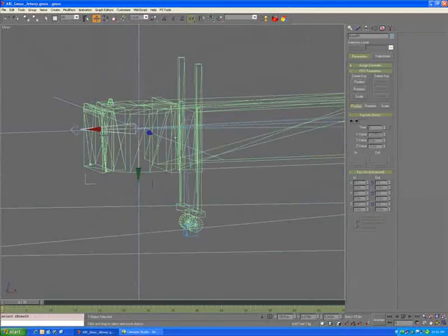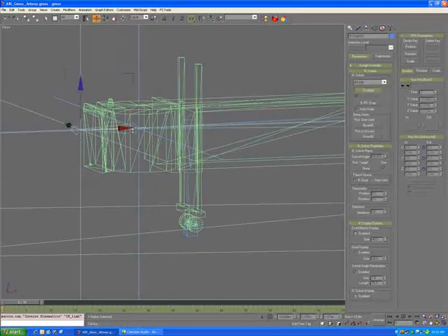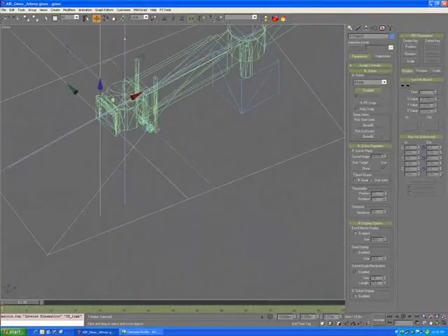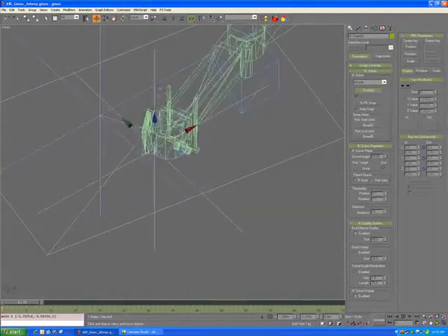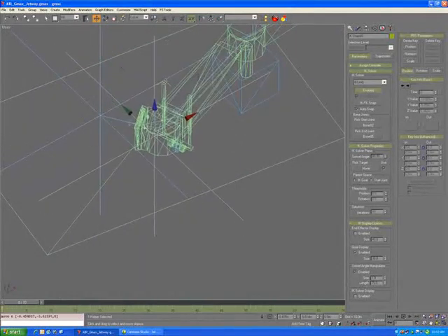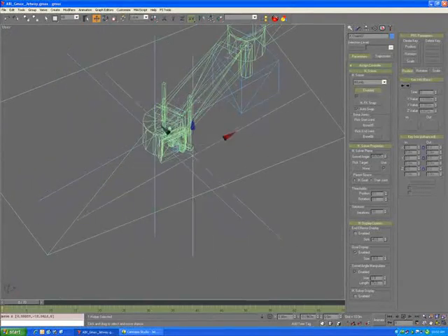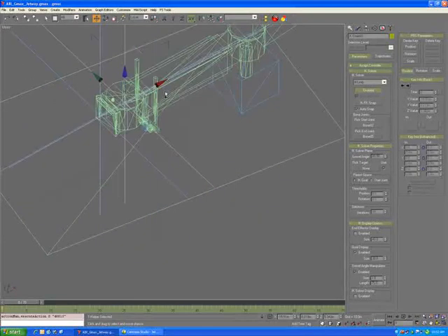So then the next IK handle you want to do is you select this bone there. Once again, IK Solver, Limb Solver, and then you go to this little one at the end here, and now you have 2 IK handles. You have one to control the main, and you'll see the main, so if I move there and then I grab this other IK handle and move it here, you can see how it would attach. And once again, you see the limits. It won't go any further than its limits are.